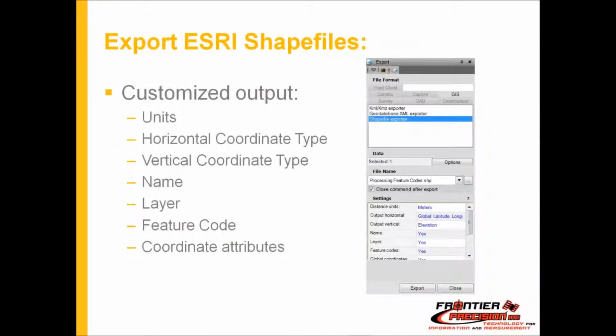All right, moving on. Also, the change to feature code processing. Now you can auto-update feature codes. So you can see in the left image there's a line ran out with this TC1 code. Let's say it was coded incorrectly. You can go through and change all the point codes to flow line, and based on the feature code library, it'll auto-update that line with the proper style and color. Previously, you'd have to go back through and reprocess the codes. Now it auto-updates as you make the changes.